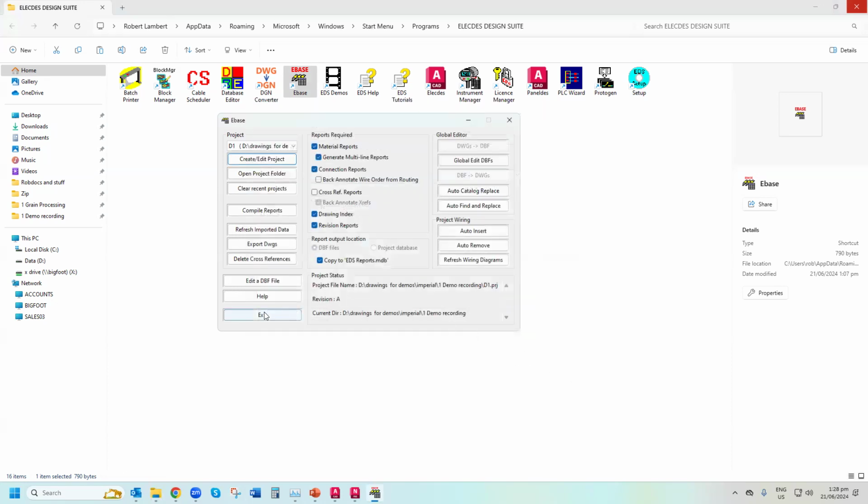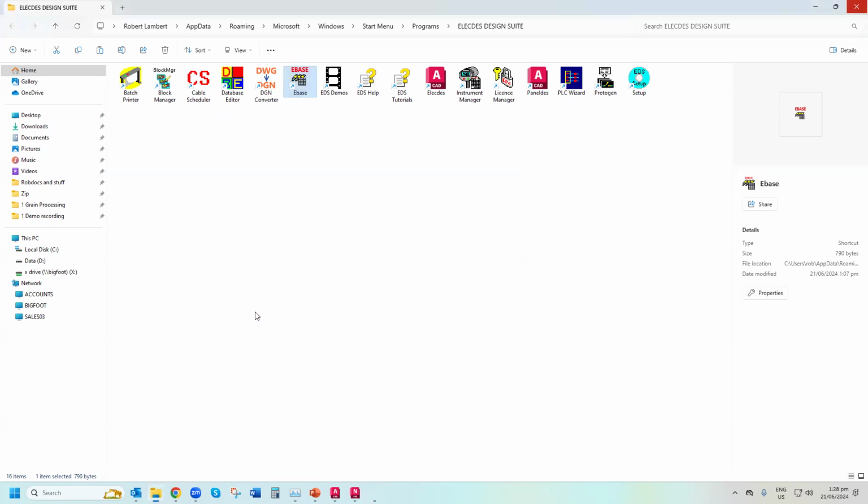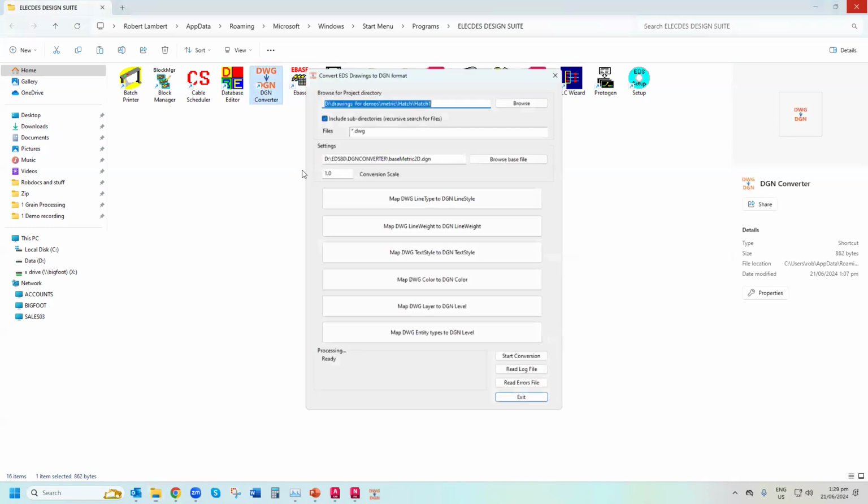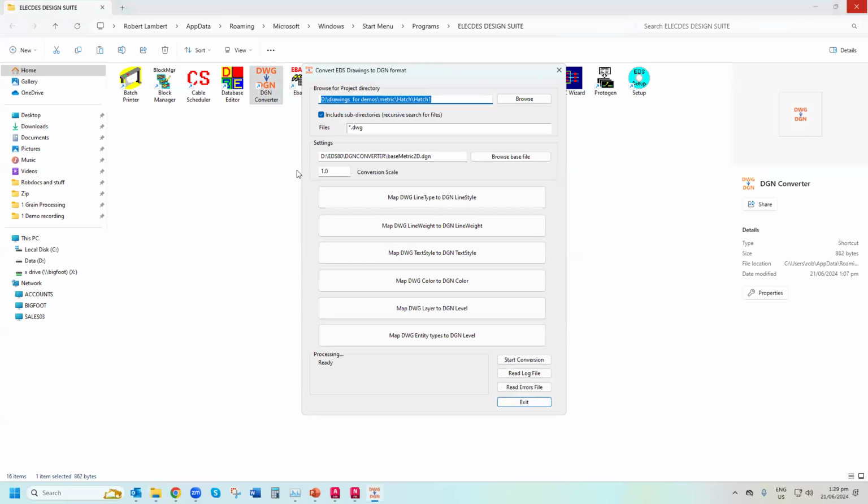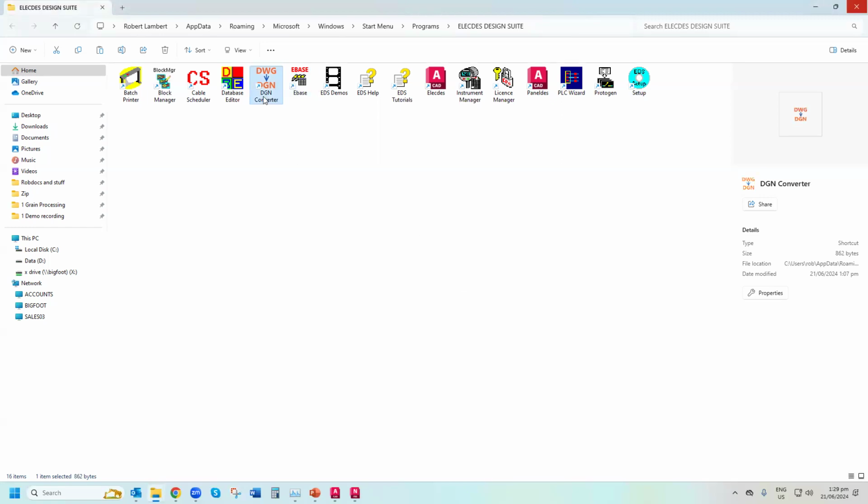While I'm in here, I do tend to show, just to explain another thing. So the data mapping started with our title blocks, and it ended up with us being able to map information to CADWorks P&ID. The other point I'll make while I'm in here again is the fact that if you encounter someone with MicroStation or that needs the output in a DGN file, we can convert to an automatic DGN file. It's what's called a block in AutoCAD, is called a cell in MicroStation, so we can convert to MicroStation without any loss of intelligence. So you don't have to buy MicroStation there. But that's by the by. So let me get back to the other screen again.